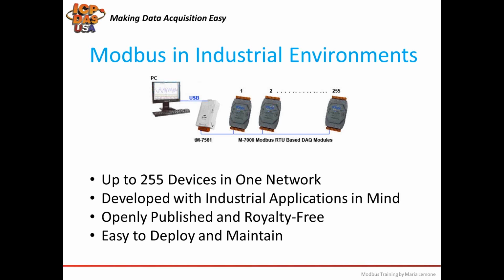All Modbus commands contain checking information that ensures commands arrive intact. The basic Modbus commands can instruct an RTU to change a value in one of its registers, control or read an I/O port, as well as command a device to send back one or more values contained in its registers.